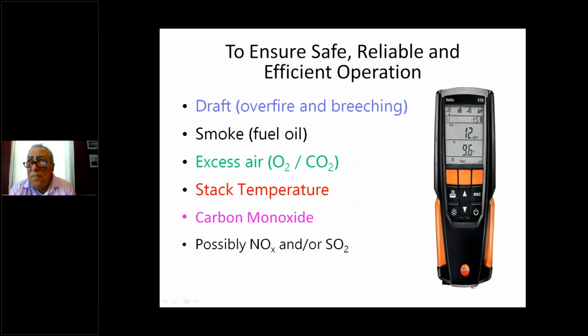A couple more about, again, excess air. What would be the optimal excess air? How to maintain 0% O2 in the stack so that we can optimize heat losses? I guess what Jane is asking is, is it possible to optimize the O2 percentage to 0? Oh, no, my goodness, no. If you can't do that at all, you're never going to see 0.